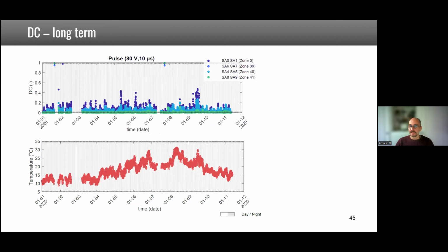And if you look at the DC, the decorrelation coefficient, you see that, yeah, it still reacts to temperature, because even though it's not as high when you have a repair, you have at some times here DC up to 0.4. This is quite high, 0.2, 0.3. So even with this technique, we are not able to have really something flat. And you see that putting thresholds on this is complicated, because there's still some trend related to maybe the high temperatures, etc., in the data.